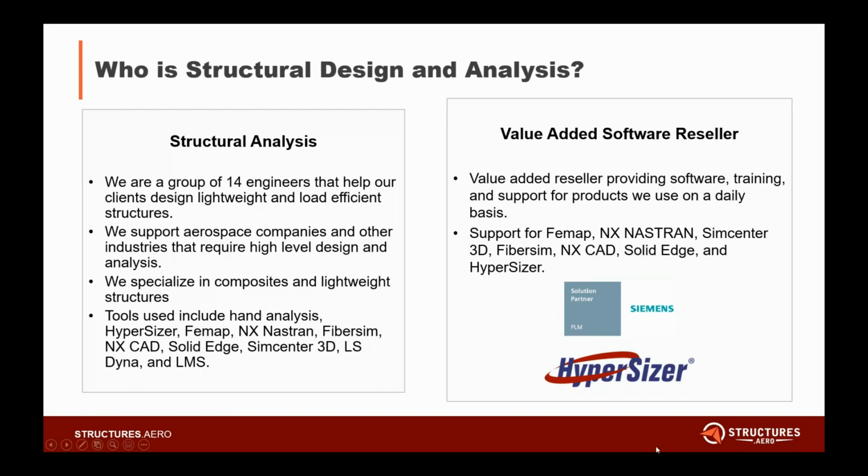Question on, can you use mid-side node elements to reduce the number of bad elements? So that's a different mapping, right? The mid-side element actually uses interpolation functions that are of higher order. The interpolation functions that I presented are very basic linear interpolation functions.